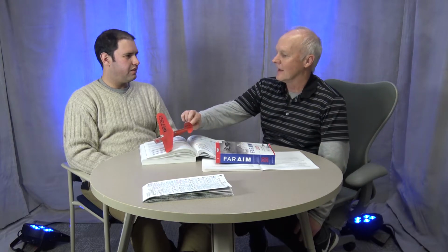And if it's the slightest bit off, it can be a mess. I had a friend, we were trying to dial in his RC plane, and it was flying like it was tail heavy. I could barely control it and get it down. He was nowhere near ready to fly it. We looked at it, we saw some wings were warped, we got them straightened out. It still flew crazy, and it turned out in one of his crashes when he rebuilt it, his horizontal stabilizer had the wrong angle of attack.